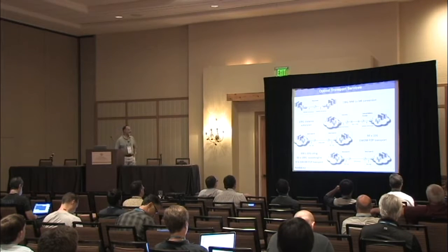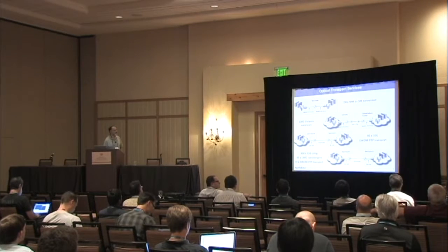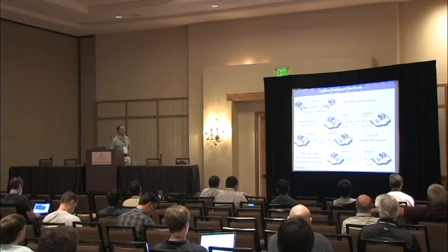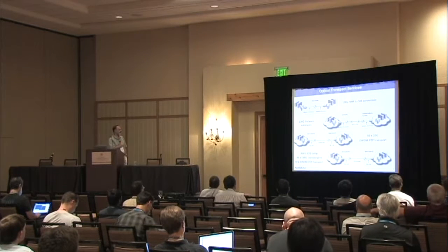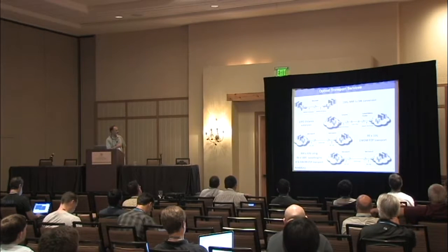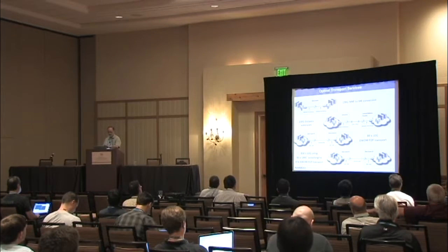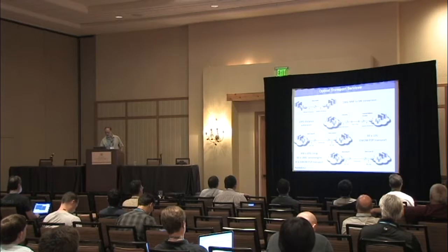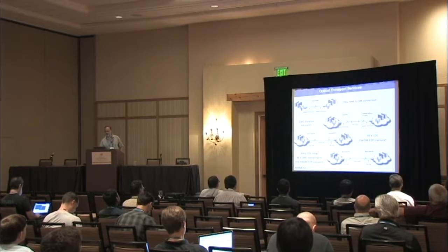Going to DWDM, same two locations. Take a few wavelengths, 1, 2, or 80, and just multiplex them together on the same point-to-point link, and you have a DWDM link. And we can migrate to 100 gig today and get to an incredible capacity of 8 terabit or even 9.6 terabit using 80, 100 gig wavelengths. So all these are real services that are deployed and will be deployed in 2014.